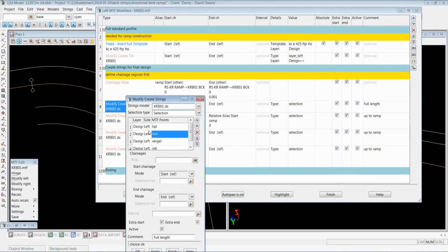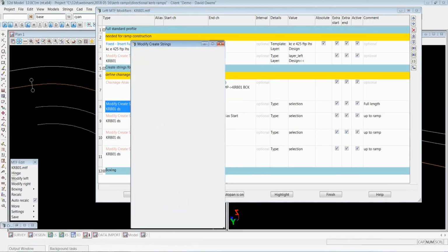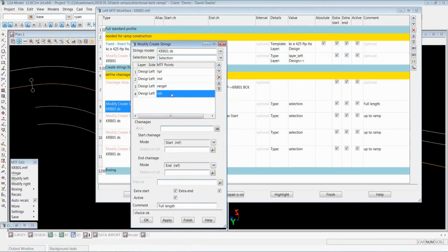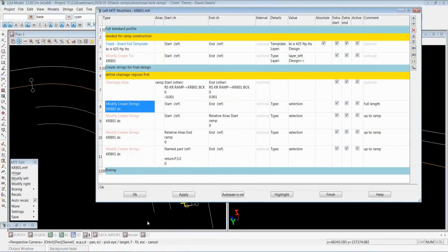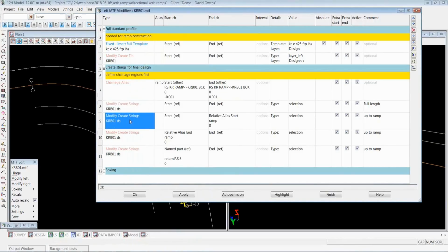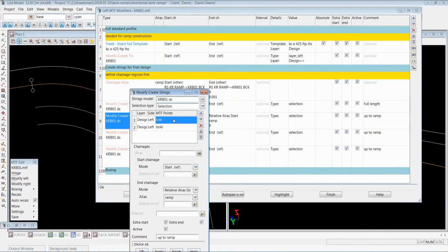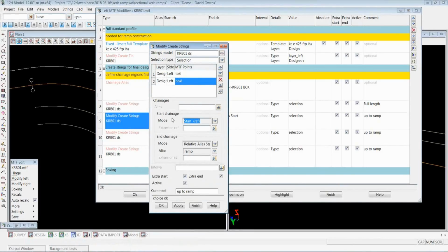And those are the strings running along the lip of the curve, the inverted curve, skipping all the stuff in the middle, so skipping the top of curves, back of curves, footpaths, all those kind of things, going right out to the verge line, right out to the very edge and to the interface, to my batter. So they're the only parts of my template that I'm turning into visible real strings over the full length of the curve return.